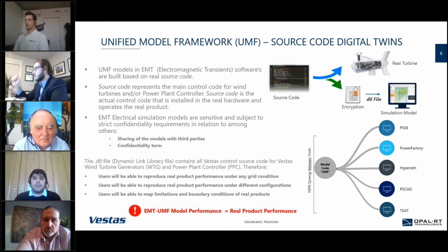Internally in Vestas, we have adopted something we call UMF, a unified model framework, where one single DLL is reusable regardless of the simulation tool. So when we deliver a simulation model, regardless of whether it's PSCAD or PowerFactory or whatever, they will always call the same DLL and the same control code.